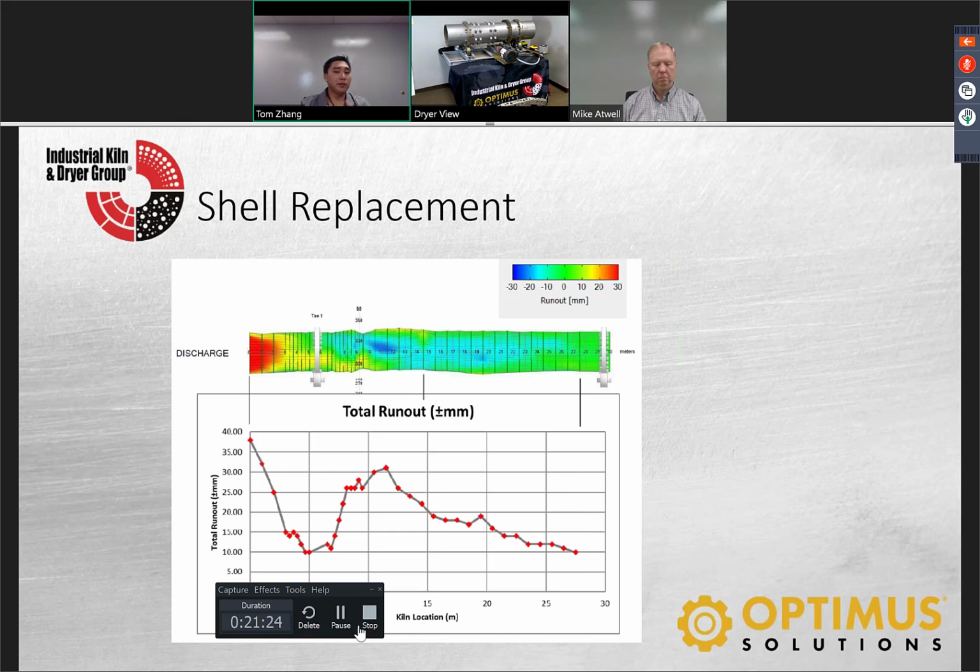So our view was, okay, hey, we have to repad, and you're already considering a repad in 3 months, 4 months, something's off. So we did an investigation into it, and we saw that the shell under the tire seemed profiled or shrunk in where there's a big divot. So we talked with some of our internal groups: hey, there's a divot, you probably need to replace the shell in this section. So we said, okay, before we say just replace the shell, maybe this is more than just that spot.